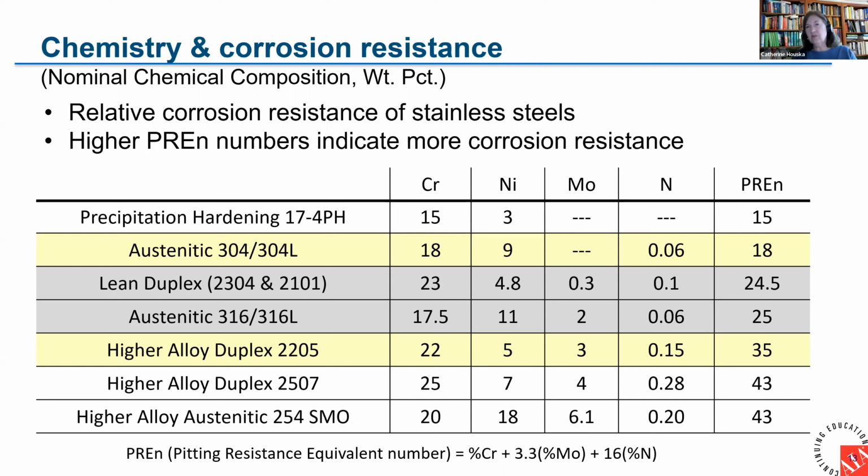The stainless steels that are up in the 40s could be immersed in sea and brackish water or an industrial stream and not corrode, depending on the choice of alloy. 316 would definitely corrode if you put it in brackish or seawater. So the level of corrosion resistance is important if you need long-term performance, especially if you want stain-free performance.